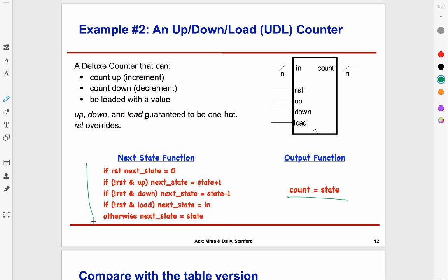Looking at this, anytime you have if then else, you start thinking of multiplexers, because that's how we steer the flow of logic in different directions. We have seen examples like when we did the median in the first homework, where you use multiplexers. We looked at the data and then selected different options. This is precisely what is going on out here.